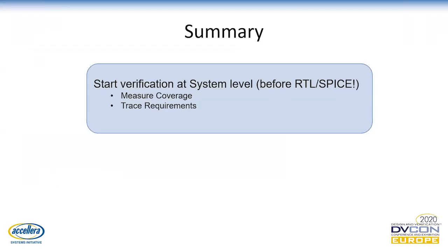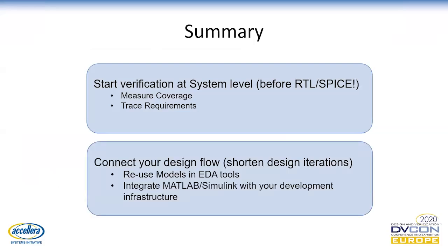Summary. So what did we have here in this presentation? You can start verification already at system level before you have any RTL or any SPICE, also before you have any software. You can measure the coverage, you can trace the requirements. After that, you can connect your design flow, so the shorter iteration cycle of different steps that you need to go through, so you can reuse the models in the EDA tools. That's what we were talking about now in my part, and integrate MATLAB and Simulink with your development infrastructure.